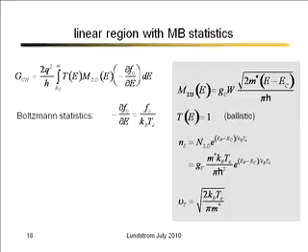Now, when you do this integral, you can start lumping things into things that you recognize. And when you do that, you'll find that the conductance is proportional to width. That makes sense. If the transistor is twice as wide, it should have twice as much conductance. If you start lumping things, you'll see it's proportional to the sheet carrier density, the number of electrons per square centimeter in the channel, and then we get a thermal velocity divided by 2kT over q.